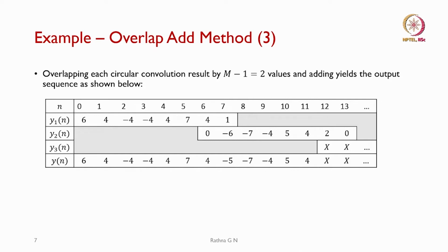So, when you write your code in MATLAB or in C, you can verify it, and for a larger x of n sequence and whatever filtering you have to do, you can use that and run it. So, in the lab we will demonstrate whether it is going to work or not. This is one of the ways of computing the long sequence using the overlap add method.